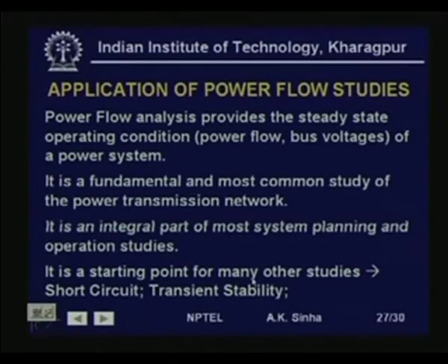It is a starting point for many other studies. That is, power flow is not just for steady state analysis on its own, but is the starting point of many other kinds of studies, like a short circuit analysis to find out what the current flow in a transmission line is, or what the voltage is going to be when a short circuit occurs at a particular point in the system.